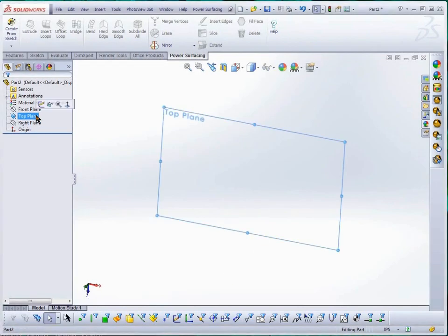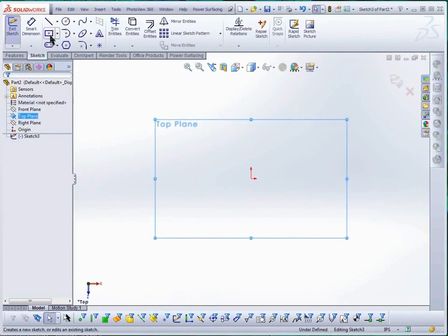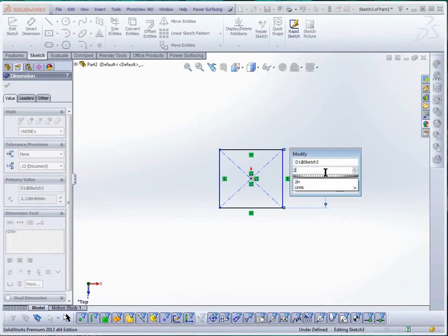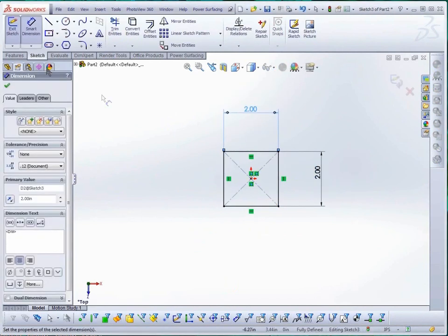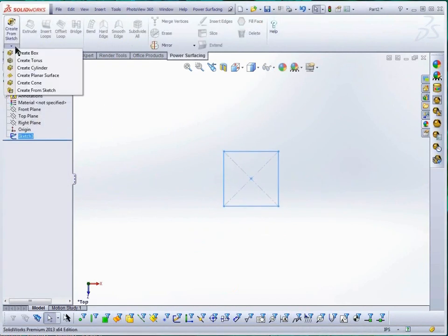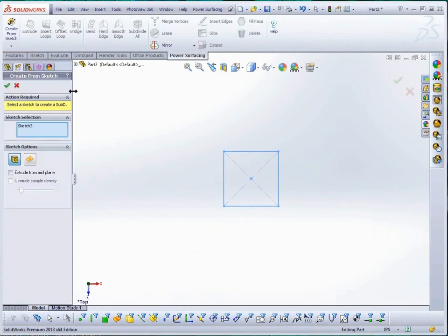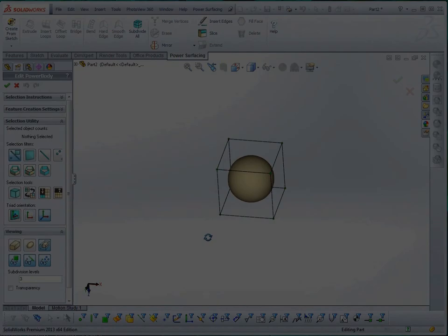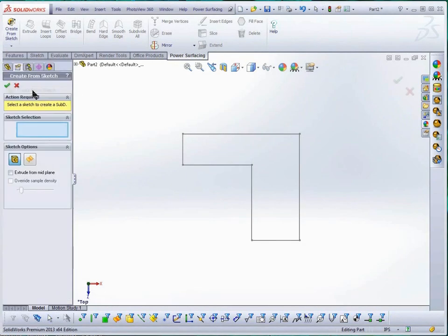The third way to start your sub-D is with a sketch. This allows you to start with a predefined location and orientation. With Create from Sketch, you have two options. As a mesh, the sketch can be extruded up from its construction plane, or both directions from midplane. Sketches over 4 sides will use only the bounding box, so keep it simple.